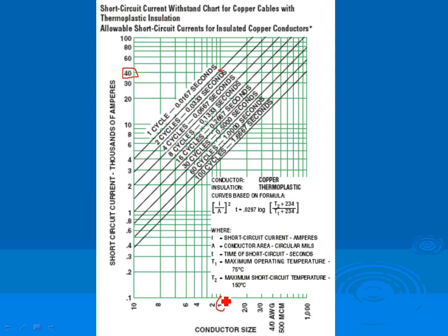Now, say I don't want to trip at 1 cycle. I want to trip at 100 cycles, because I want to see what I can do. If you set your circuit breaker to trip at 100 cycles, what size conductor do you need? Now I'm exaggerating here because nobody will set the instantaneous to trip at 100 cycles, guys. That's eternity. That's the conductor sitting there and being cooked.